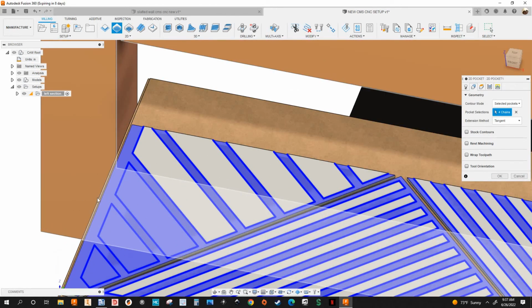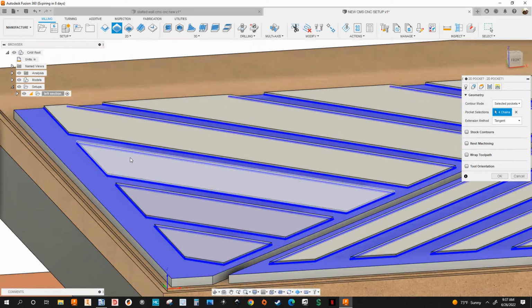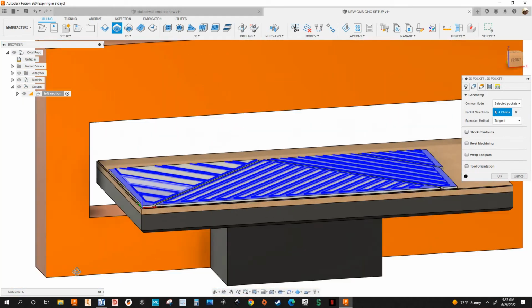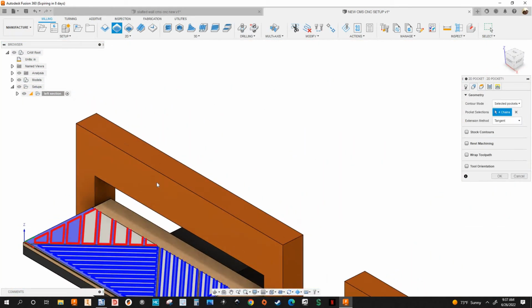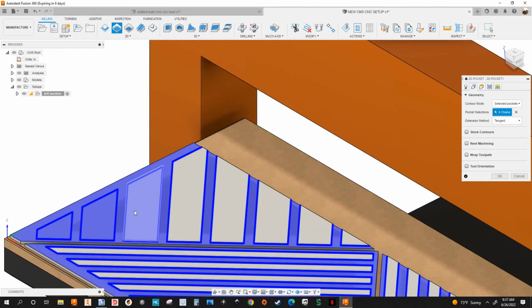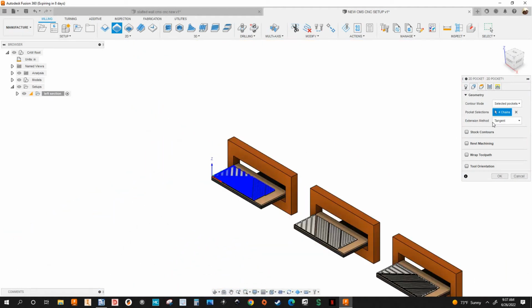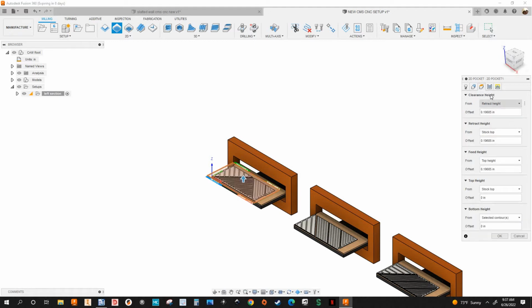Seems like it's selecting the top faces. Okay, let's leave it like that, right? We're gonna see if the machine's gonna machine through these pieces right here in the simulation. Okay, so the section method is tangent. On the height tab, I'm not making any changes. Under passes,